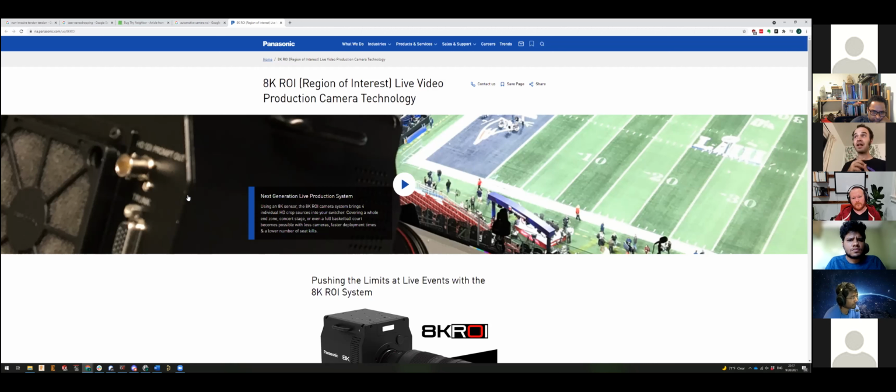But then we get into our Nyquist frequency thing, because if we're looking at something very far away and we want good spatial resolution, we need to not bin, because following that law, we can only measure a particular edge rate of change, or spatial resolution. Let's say we're trying to read the speed limit sign very far away. We can only make out that typeface if we have, say, three pixels of width. If you bin that down, you lose it.